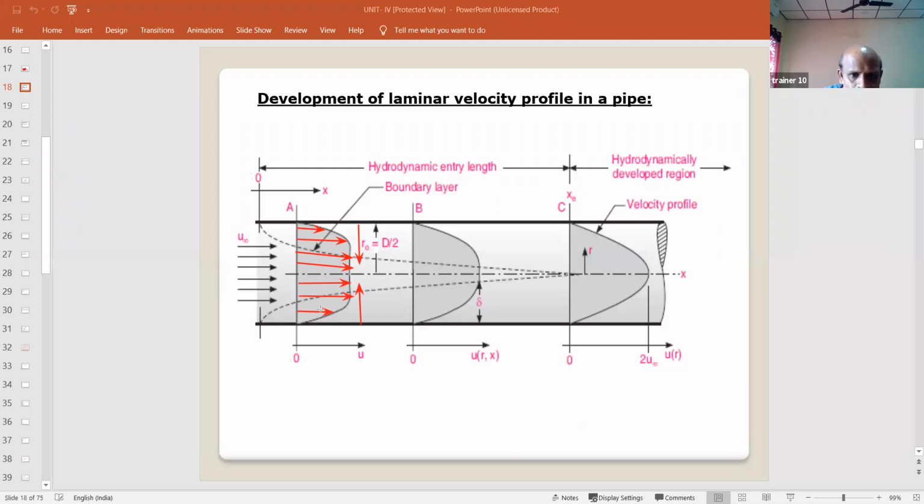Okay, so this is the velocity profile at A section. Similarly, if you consider the B section, then what happens? At the walls, we have zero velocity only, that does not change. But if you see the shape of the velocity profile at this section, this is the shape, and at B the shape changes in this way. So that means at the radius of the pipeline, the velocity further increases.